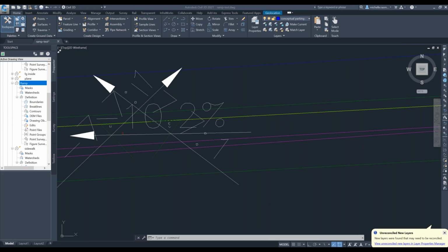But essentially, yeah, we do not have a great process right now in place for the number of ramps that we have to deal with. So unfortunately, we are mostly doing a final layout on site with certain constraints and specifying typical ramps that you might find. But we have some roadways with 30% grade, many with 10% or more grade.